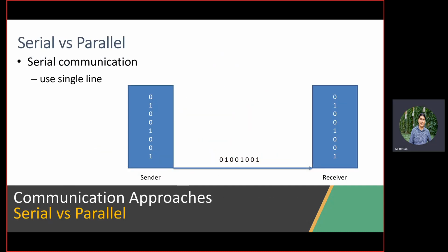Okay, so given that we mentioned GPIO as a general input-output device, which is the easiest, might even be dumb information for you, but let's abstract a little bit, something theoretical. Regardless of the protocol you are using, there are different technologies or categories of protocols, and we'll try to categorize them. First, there is serial versus parallel. Serial communication, from the name, is just sequential bits. You have a single wire that you keep sending bits through, right?